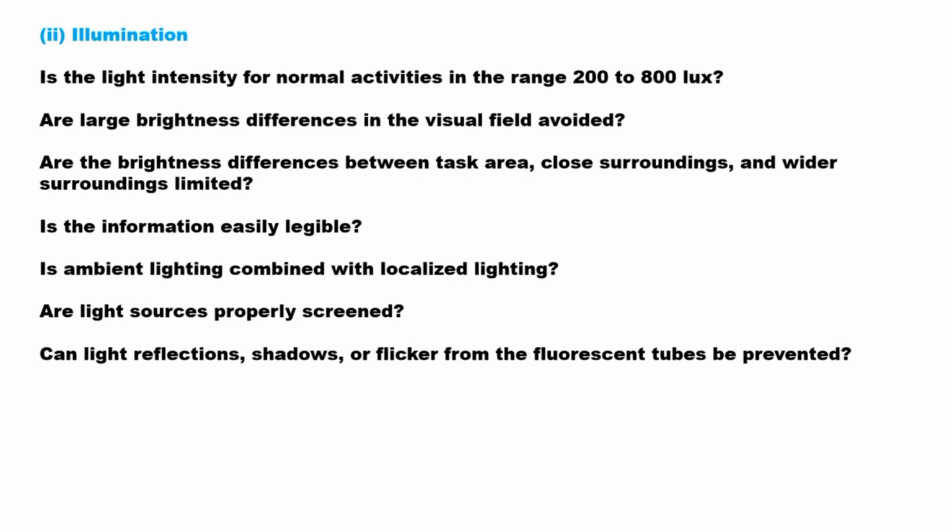E. Illumination. Is the light intensity for normal activities in the range 200 to 800 lux? Are large brightness differences in the visual field avoided? Are the brightness differences between task area, close surroundings, and wider surroundings limited? Is the information easily legible?